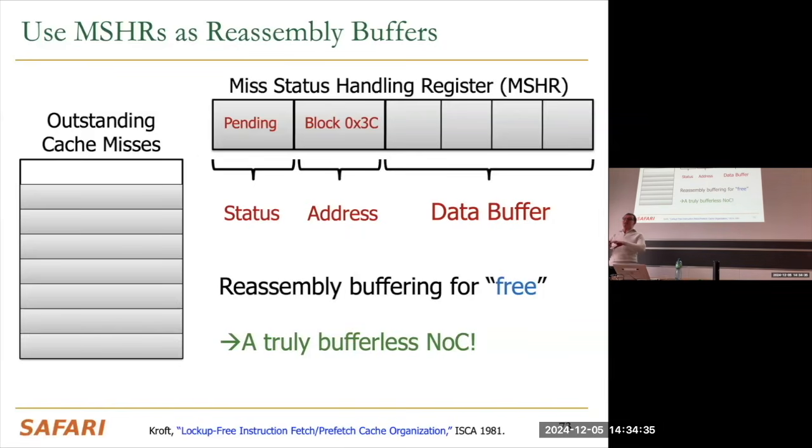But of course, this requires the design of basically the MSHRs together with the network. If you actually have separation, like if you're in a company where two parts don't talk to each other, somebody designs the MSHRs from the on-core, and then somebody else totally different, in a totally different department, designs the router, the router people will say, oh, I have buffers.